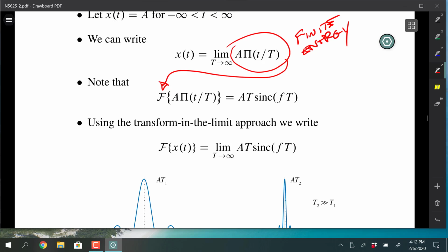We should be taking the integral with the limit on the inside, so it's infinite in duration, but then we can't Fourier transform it, right? Because it has infinite energy and the theorem doesn't work. So the big thing about Fourier transform and the limit is do the limit after you take the Fourier transform of the finite energy signal representation.